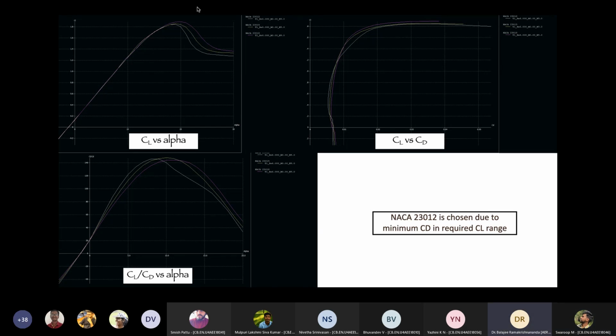In the textbook, he can't put values for all airfoils, right? So he has generally assumed in airfoil theory that it's 2 pi. That is the maximum possible. For a thick airfoil, there may be slight deviations, maybe less than 6.28, maybe only 6, we don't know. Measure from the graph, in the linear portion of the graph. It was 6.6 something. 6.6 is too high, it won't be. It cannot be more than 6.28. We'll check once, sir. You will get it in degrees, the graph will be in degrees. You have to convert it to radians and compare. Okay.